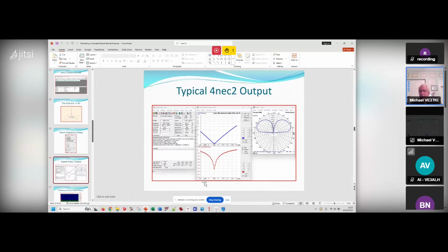Well, Daniel and I are thinking maybe we can do something on 80 meters with my vertical antenna. You'd have to put a matching coil on it to get the length right on the vertical piece, and the two radials would be huge probably, or maybe change the coils, but do it that way. But we haven't done that yet.